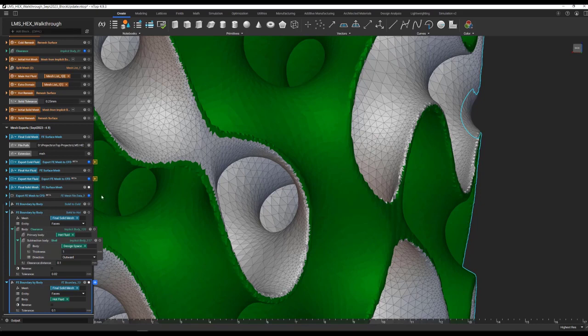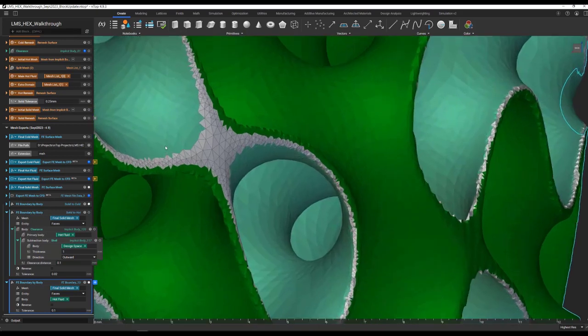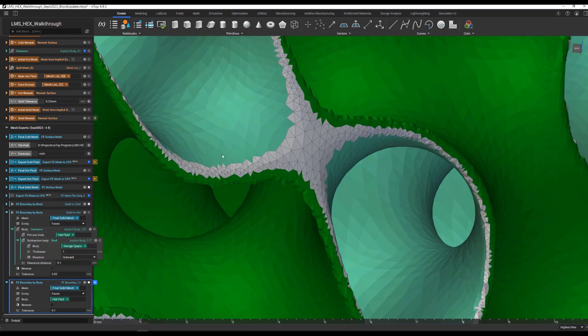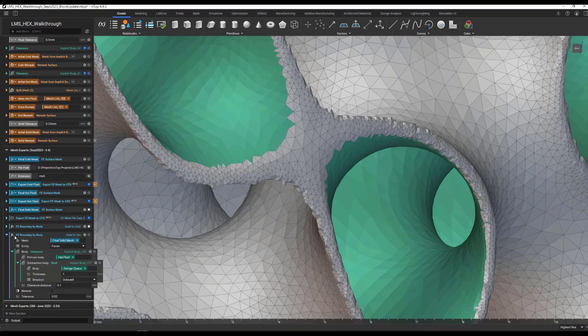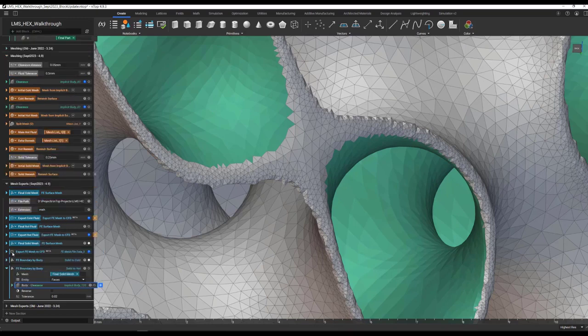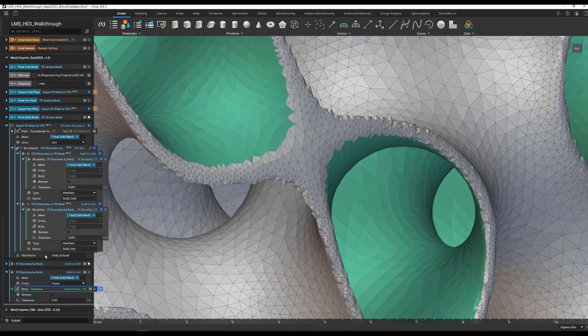And if we happen to share elements with the opposite interface region, ANSYS can sometimes get confused with that as well, and we actually won't even let you export an FE model like that. So a little bit of a nuanced step right here, but pretty simple and straightforward once you understand it and implement it a couple times.